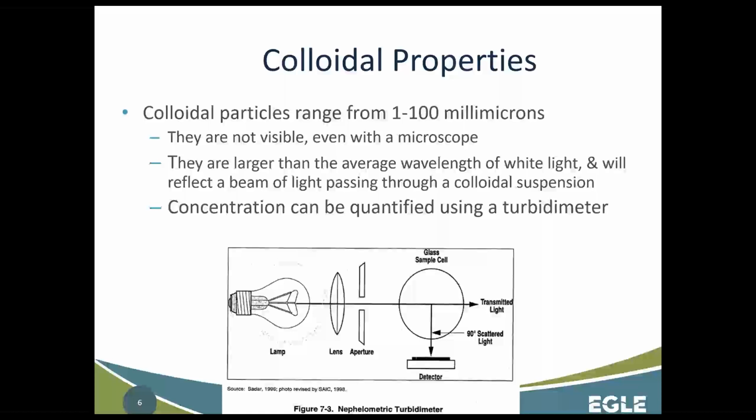And this has been the method that's been used for a very long time, although, like I said, we've come a long ways in terms of what these turbidimeters look like. Some of the more simple devices that rely on this principle is like a Secchi disc. Some people may have those at the plant for taking a quick look at turbidity. Basically it's just a disc that has contrast in colors, usually black and white. You lower it down into a water column, and then you measure however far you can lower it before you can't see the disc anymore. It's a way to quantify how turbid the water is. That's a really basic method that relies on the same principle.